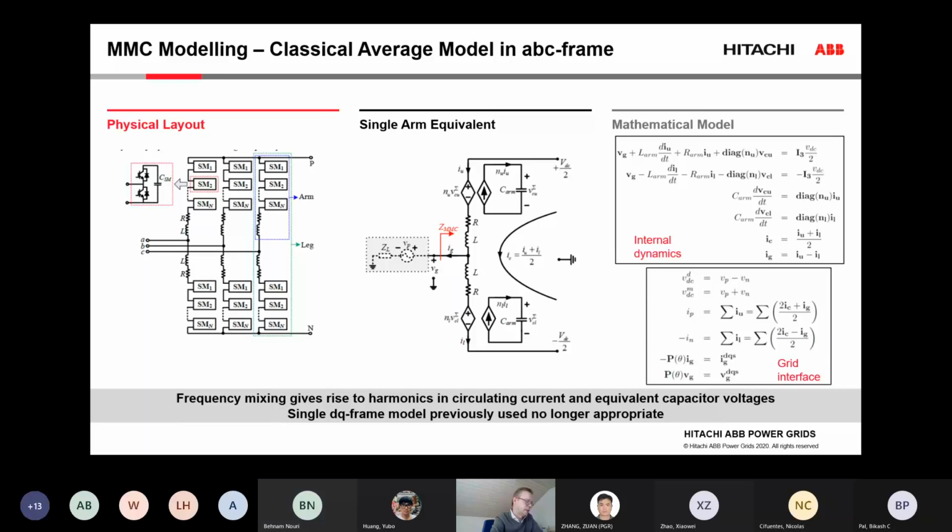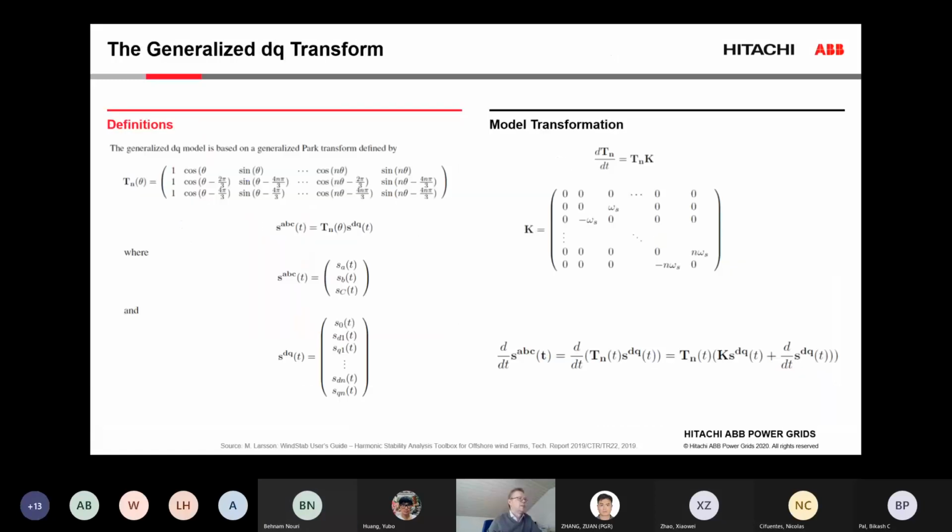And this is because we have a Y delta transformer. And the other assumption is that the zero component doesn't pass through. The zero current, the zero component doesn't pass through. And that gives you enough assumptions to handle the case of approximation order 3. Then you still have enough equations to go both ways. But you have to add these additional assumptions.